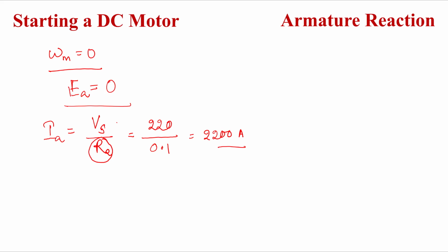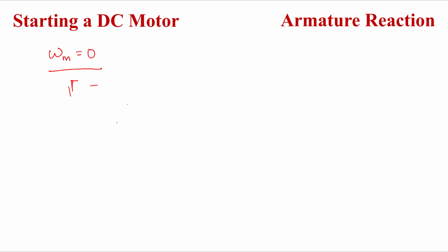So therefore we should never start the motor by turning on the switch, particularly DC motors, right? It will immediately burn your motor. And you should take this precaution in your lab very specifically. Don't start the motor just by connecting it to the supply and turning on the switch. It will damage the whole motor, then you will have to pay the penalty. Maybe 20,000 rupees. Okay? So don't do this. Therefore, we never start a DC motor just by connecting the supply and switching it on.